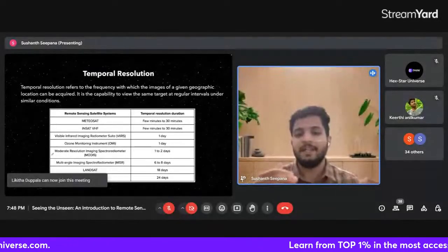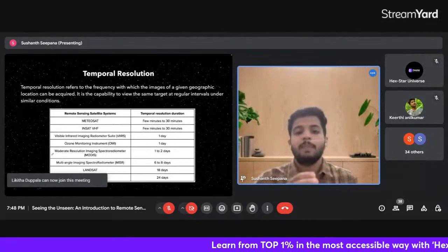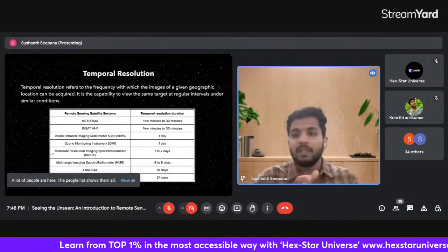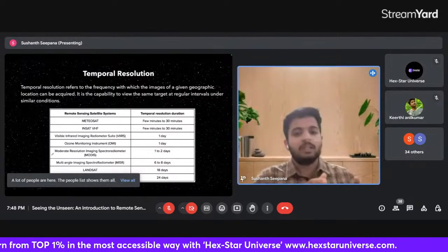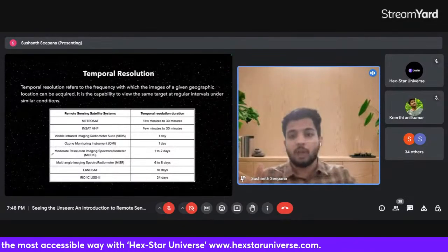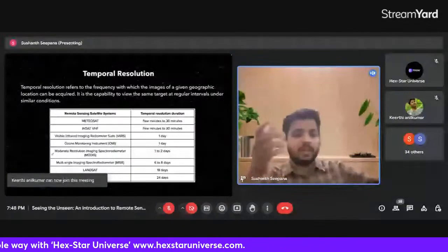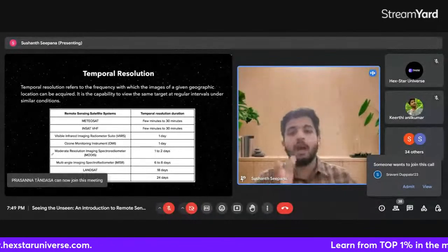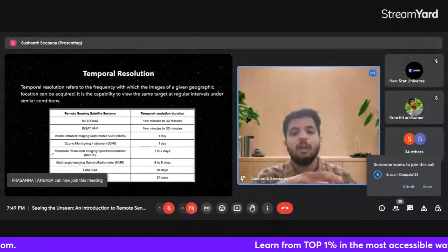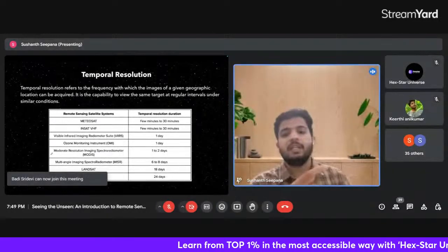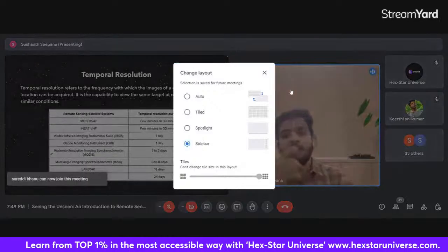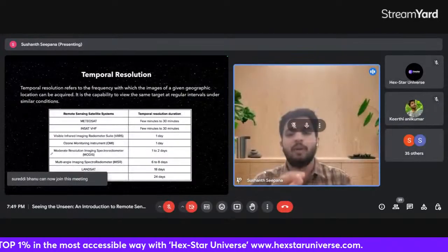Landsat is able to cover in 18 days. This is because MODIS has a higher swath width, and the spatial resolution is 1 kilometer. So it can cover, let's say, thousands of kilometers in one revolution, thousands of kilometers or hundreds of kilometers in a single revolution. So the entire Earth can be mapped in a single day. Let's say it takes 1.5 hours or 2 hours. In 12 times, it can cover the entire Earth with some overlap.